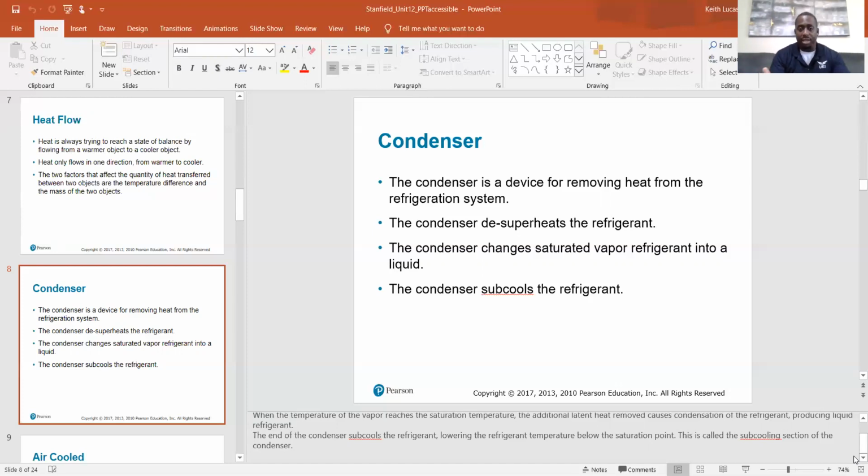So that's how the heat is being removed. I think some of the explanations need to go together. This chapter is not talking about condenser fans, but I feel like it was necessary to mention because they're just talking about de-superheating like this is just some automatic thing that happens just because you're in the condenser. What happens is the condenser fan is pulling the cooler outside air across those coils, and the heat transfer takes place,